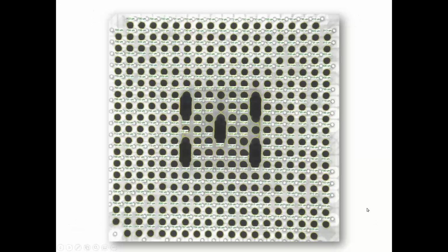And we can see this, and we can measure the degree of change if we have an X-ray system which allows direct measurement of spheres. So this is an old photograph, probably around 10 or 12 years old, but it's an experiment I was doing, and I wanted to demonstrate how you could measure and quantify the degree of warp of a package based on looking at ball size. What you're looking at here is all the balls, and they're measured, and we could argue that perhaps they may be 10 microns out or 12 microns out, but it's the relative variation that you can see.